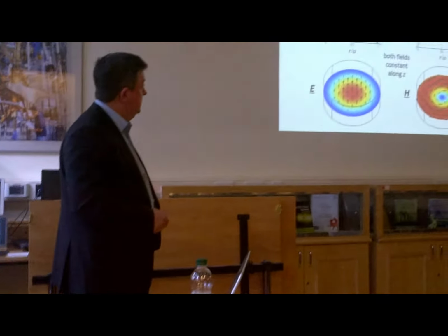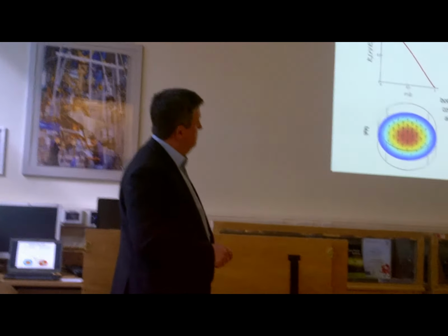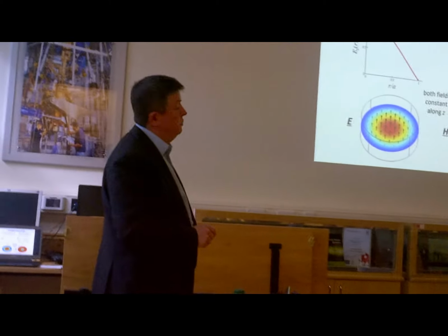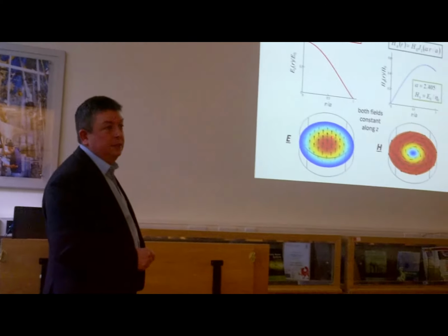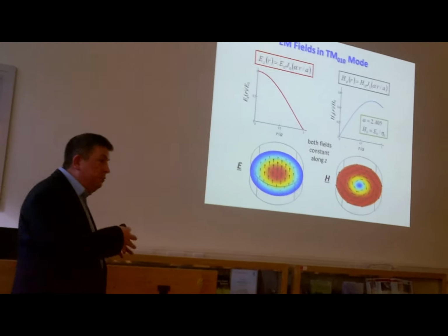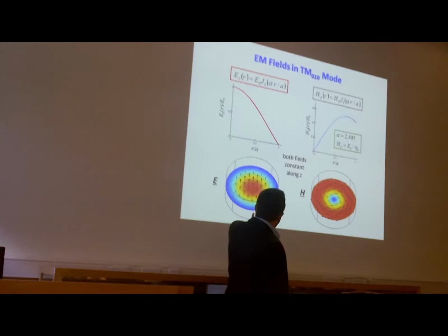But all these other ones are interesting to us because they just give you a separate mode of excitation. So we try and utilize as many of these resonant modes as possible. This one is designed here to go at 2.5 gigahertz simply because that's where microwave ovens work. And it's one of the allocated ISM frequencies.